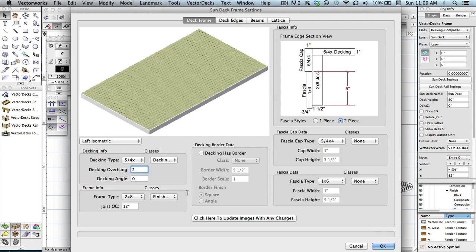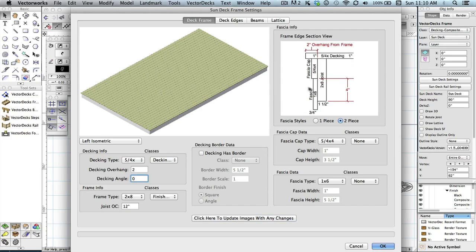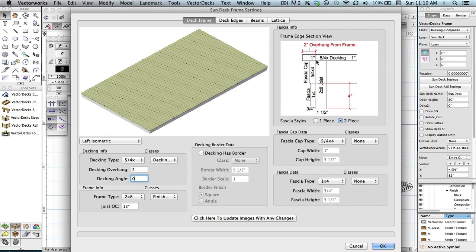The other thing too is I noticed that as I entered any dimensions in any field that had dimensions, it slowed this particular window down because it was redrawing this view as you entered the dimensions. So I turned that off, and after you make the changes you want, then you'd come down here and click on this particular button. Then it updates everything, so it sped up the process. So as you see here, the decking will now overhang the joists. The trim gets adjusted down. You could change, let's say, 1x4. So you can make your changes, and it'll automatically be adjusted with this decking overhang.